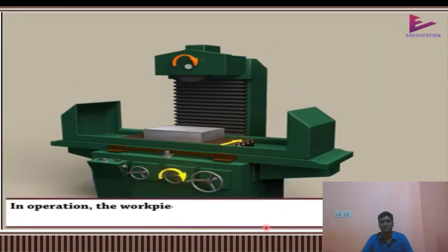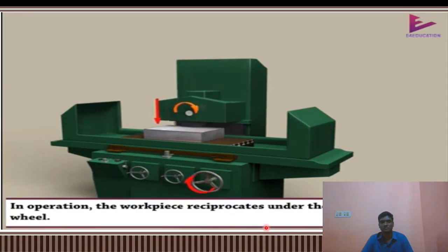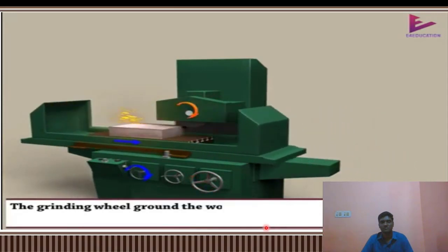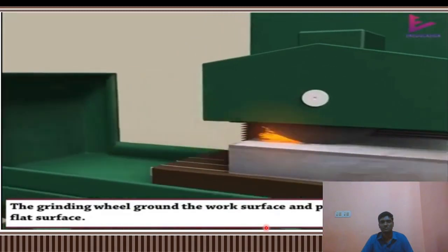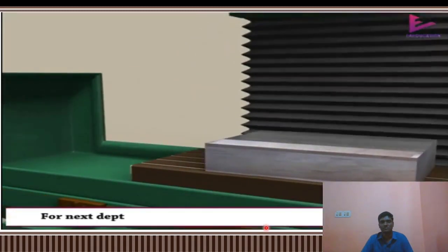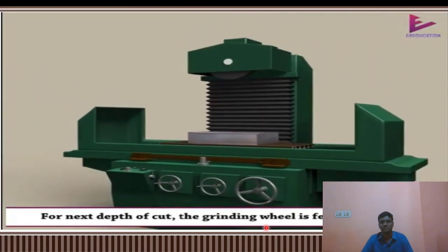In operation, the workpiece reciprocates under the rotating grinding wheel. The grinding wheel grinds the work surface and produces a smooth and flat surface. For the next depth of cut, the grinding wheel is fed downward.